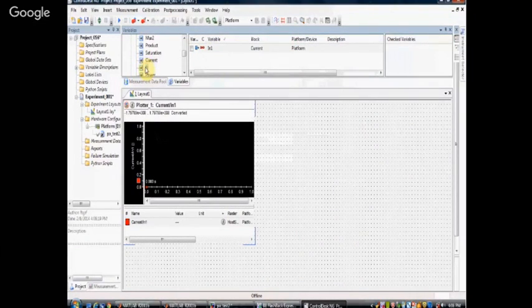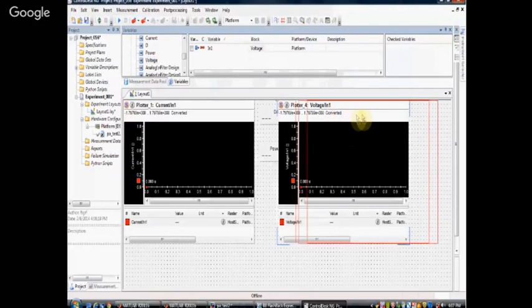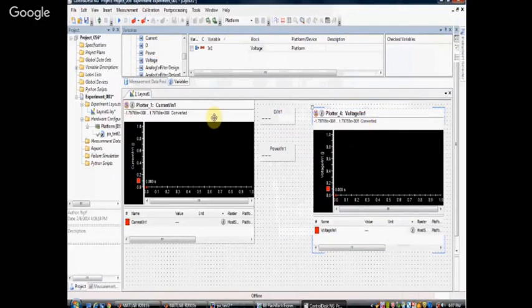Okay, so here I've seen the current. Now duty cycle I want, just drag it. If you want to see a plot or display or anything, you just have to drag and put it here. Whatever parameters you want to visualize, you can drag and put into it. Now I'm putting power and next I'll take the voltage. So I want to see what is my power, what is my current, what is my voltage and duty cycle. So all these parameters I can record.